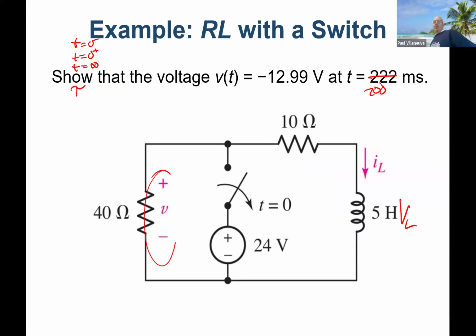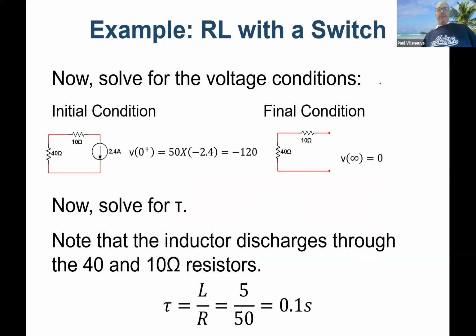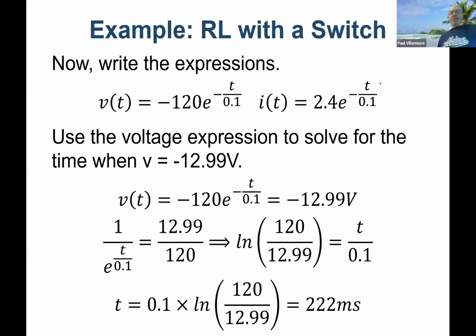Which makes sense because the voltage drop across the 40 ohm resistor is going to be slightly smaller than the voltage across a 50 ohm resistor. So that should have been 200 milliseconds. Okay. So I did that approach for that, but you can take a look and you can see what the results are. Questions on how to do that?